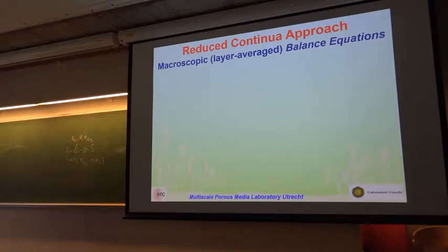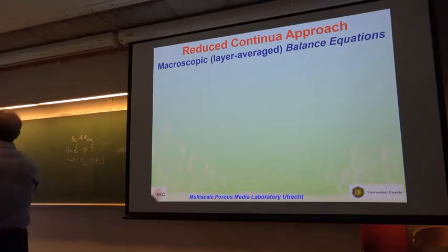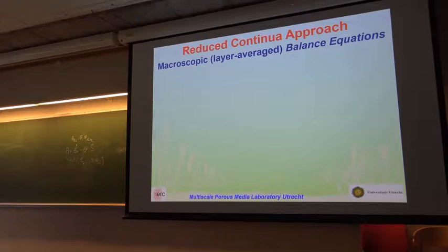But I thought in groundwater flow we have that aquitard, and the aquitard only provides a resistance to exchange of water between the upper aquifer and lower aquifer. Is that also usually what one does, add some resistance? But then typically in those situations, in that aquitard there is no significant lateral flow, so they only assign a resistance to that aquitard. Yes, so it's not modeled as a layer. My point is that even the layers themselves do not have a RAV in the vertical direction, very often in oil reservoirs. You just model it as a layer. But is there lateral flow in there? Usually there is not. You don't model lateral flow in there.